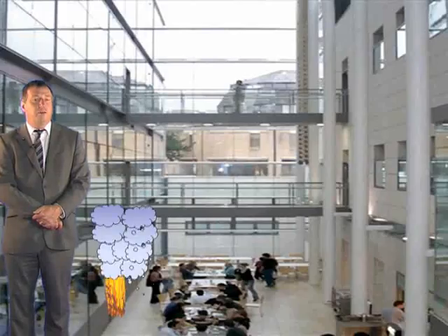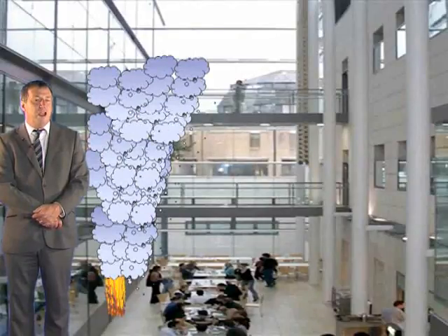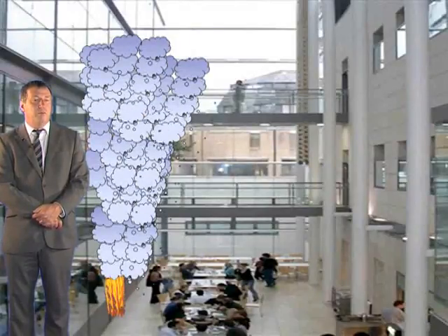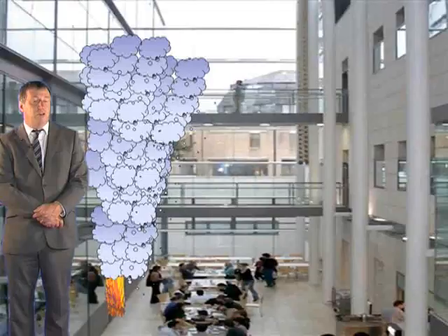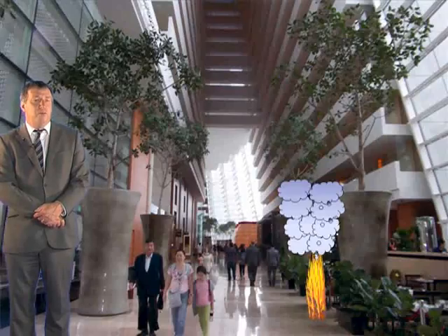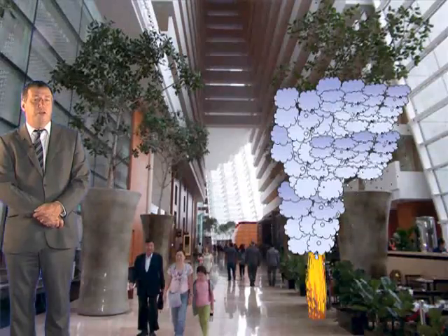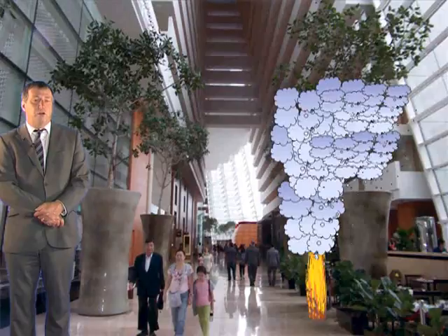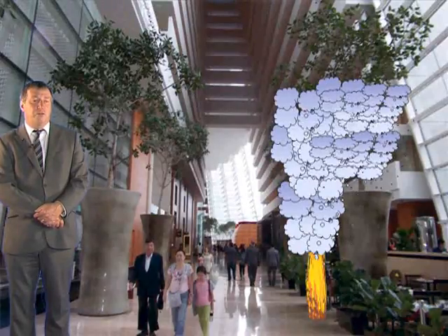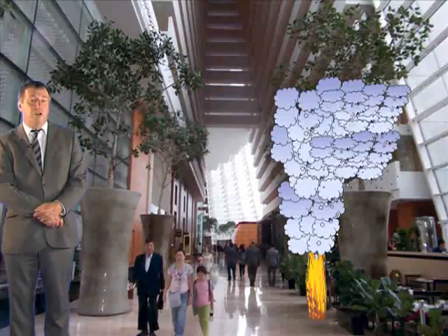If a wall in an atrium is smooth with no holes for air to get in behind a plume, then the plume is likely to adhere to the wall. And it does this because air cannot get in behind the rising plume, to release it from the wall. A free plume is one where air can get between the wall and the plume, so there is nothing to hold the rising plume to the wall above the spill edge. The mass flow rate of an adhered plume is lower than that of a free plume, as there is less plume surface for cool air entrainment to take place.